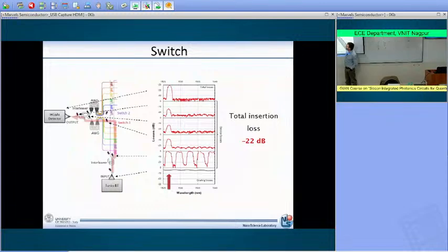switch. Okay, the single switch, you see here that we are adding from here to there. By simply switching the channel, we are adding 4 dBs. So we have 10 dBs from the gratings, 4 dB from the switches. That makes overall 14 dBs. It's too much. Okay? And this is the reason why this project was ended.